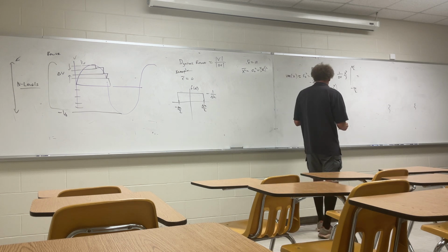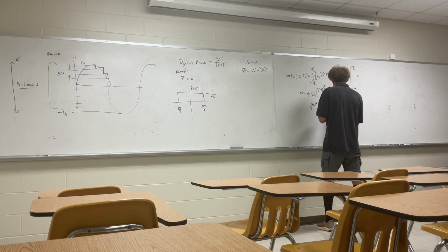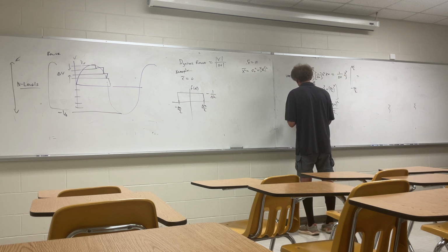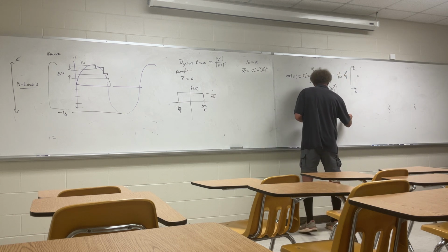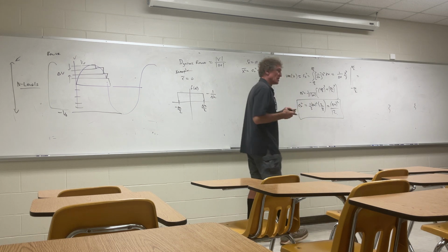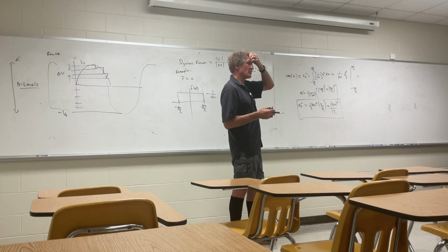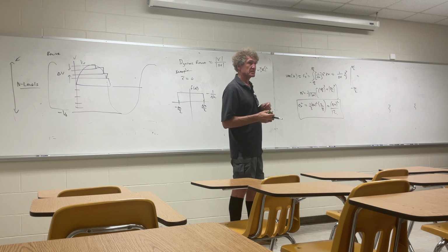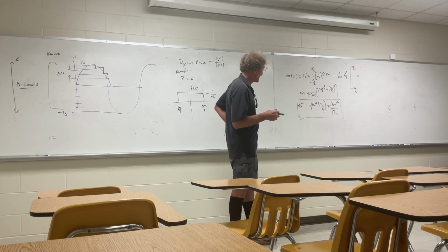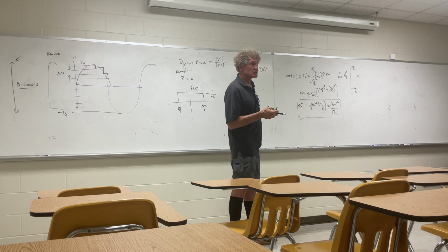Well, that is going to be delta x squared over 12. This is important. Anytime we have quantization where there's an equal chance of the event being anywhere over, it's basically going to be uniformly distributed. And this is assumed, by the way, for quantization calculation, the error calculations. You get that? Y'all with me?